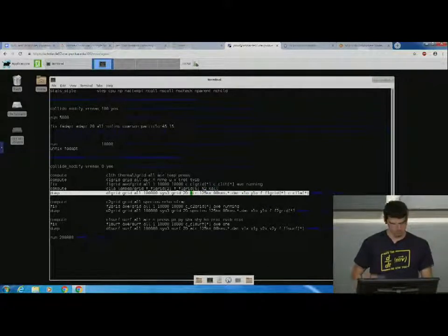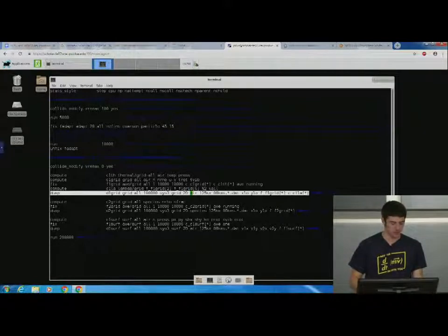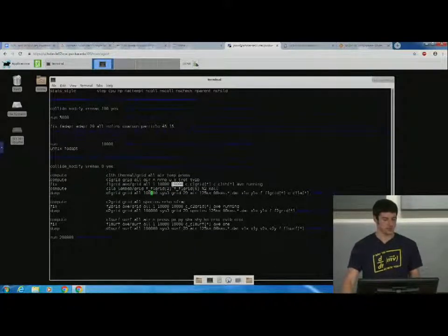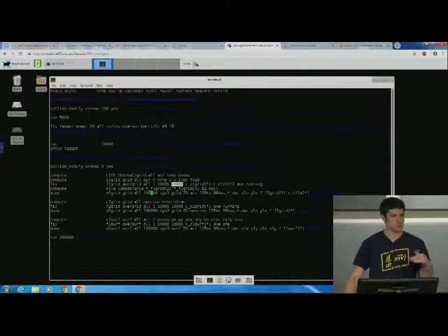Now for this dump command, here we're actually outputting our results that we just computed. So here I'm outputting the frequency every 100,000 steps. I found that it's, for some reason, better to do something that's greater than, but still a multiple of this number. If I do it equal, sometimes SPARTA outputs just a bunch of zeros. Not too sure why. So it's better to do this greater number here.